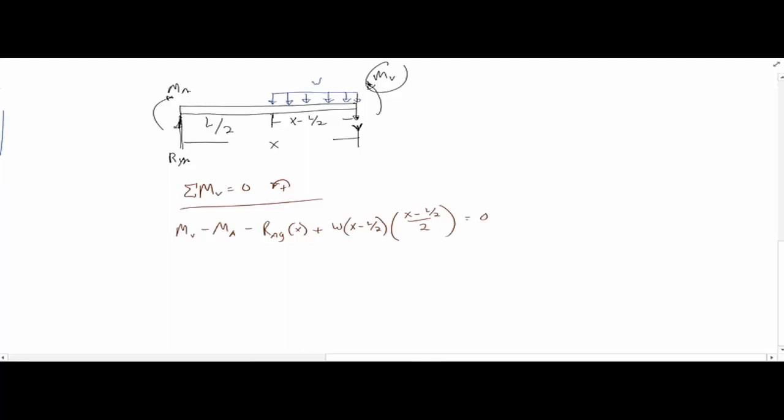So then we can reduce this down and say that the moment at x distance away, which is the moment at the shear where we're making our shear cut, is then going to equal, just reducing a couple things here, negative w times the quantity x minus L over 2 squared plus wL over 2 multiplied by x, and then minus 3wL squared over 8.